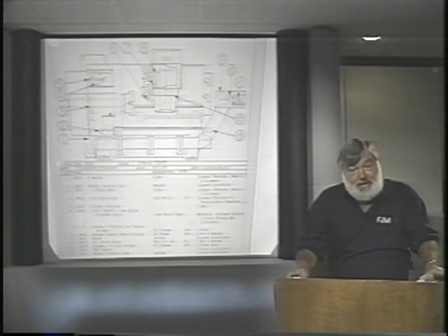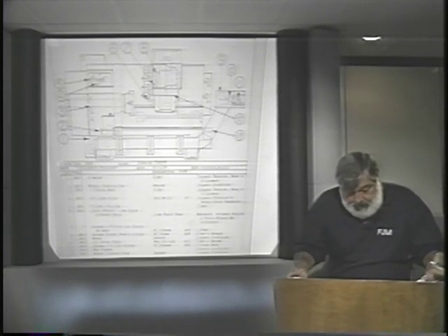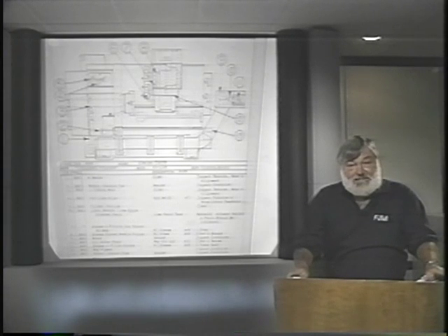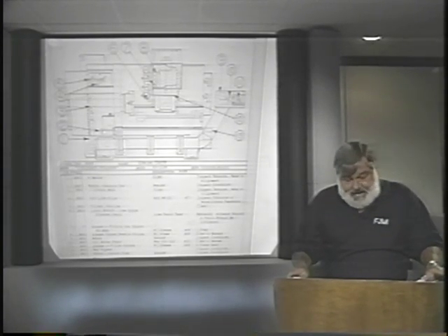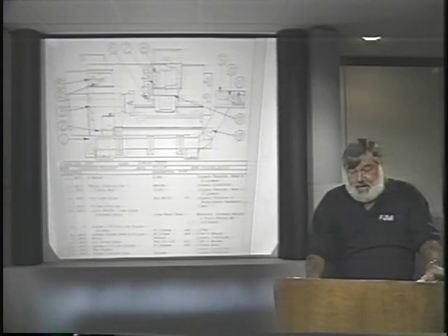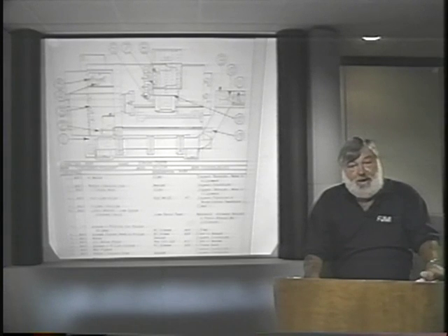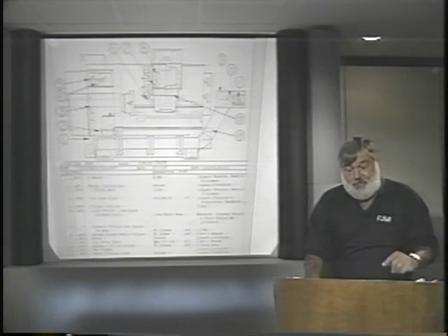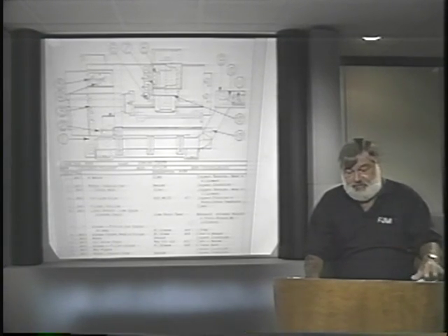It also indicates the frequency. And here, in this case, where you see 360, that says every day. So this is a daily lubrication. It indicates the type of lubricant and any other data to make certain that the operator is not using the wrong lubricant for a particular lubricating orifice.